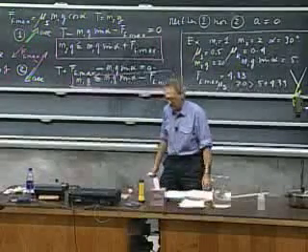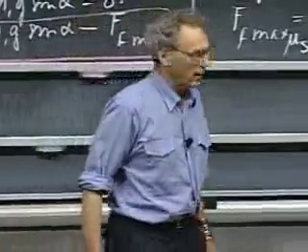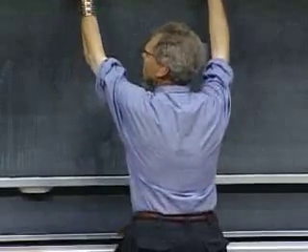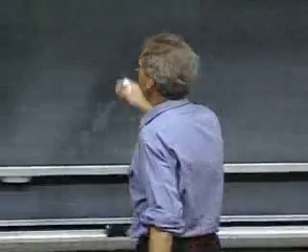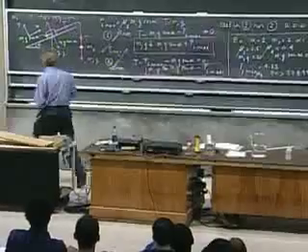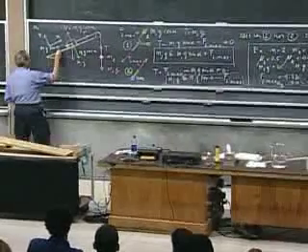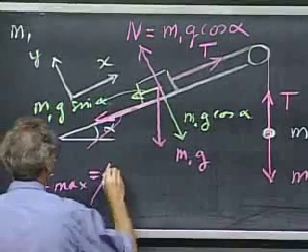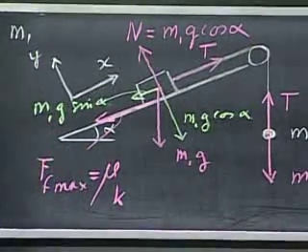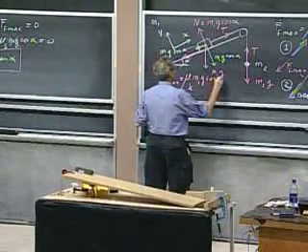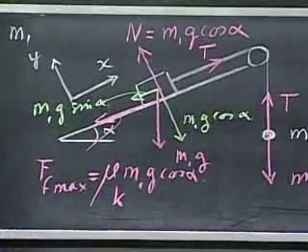So now I could ask you a simple question. What is the acceleration and what is the tension in the string? And so you will think, oh well, that is within arm's reach. Not quite, because things are now going to change. If it is going to be accelerated uphill, then at least I know one thing, which I'm going to put in this drawing now. I know that this is the maximum friction possible, which now becomes mu kinetic, because it's going to move, times m1 times g times cosine alpha. So that is already one change.